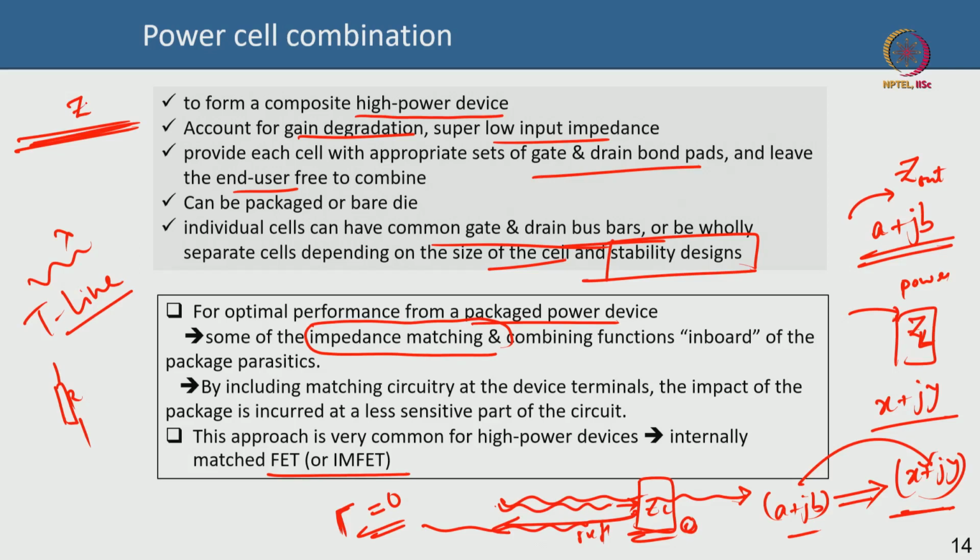That metallic line, and we will see pictures of that, will have its own characteristic impedance. You can use the metallic line with open short structure, series parallel structure, which will behave like a capacitor or a resistor, and so using that combination you can make a matching network using transmission line to represent capacitors and inductors at higher frequencies. At lower frequencies you can use a lumped capacitor or an inductor or other things that you can buy from the street market.